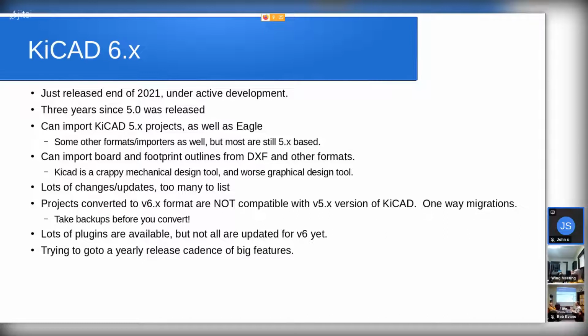So if you have a vendor of a particular component you want to put on your PCB, you can hopefully pull down that component's DXF and then import it in. Even for the Pi 4, I found a KiCAD footprint that has all the pin placements for the GPIO, because the thing I want to design is a Pi hat. And I was able to find a KiCAD footprint.